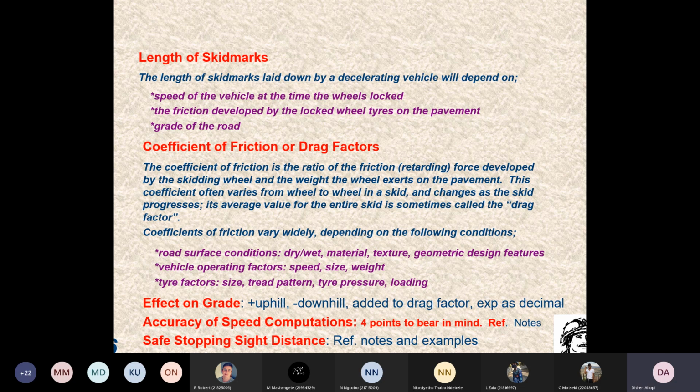You wouldn't draw a straight line there. Can you imagine a vehicle going up a stepped effect? It's certainly not good for any driver's tummy, isn't it? So that is why we link our grades by means of a vertical curve. And you know the basic principle behind vertical curves. It's a parabolic function, ax squared plus bx plus c. Therefore, you have a gradual rate of change of grade.